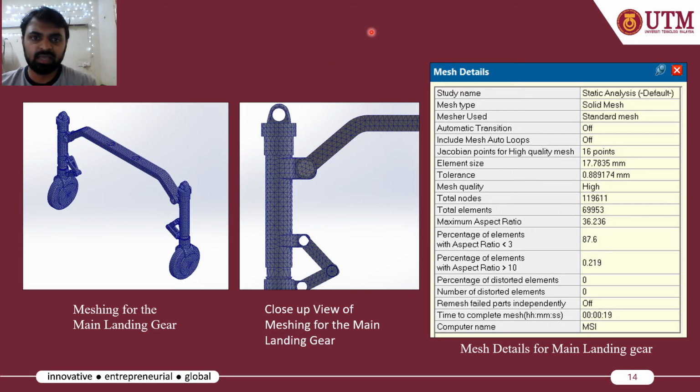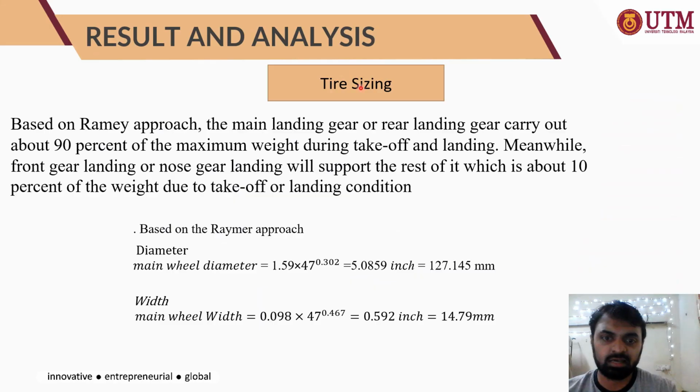Generating the mesh is the last step of the modeling before starting the analysis. Generating the mesh is one of the important aspects to be considered, because it will produce better accuracy of the result. For the project, the mesh that we use is triangular or tetrahedron faces that connect to each other with the face and the node.